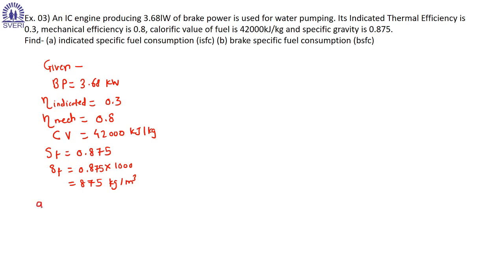So I'll start with part A, that is ISFC. So we know the formula for ISFC is equal to fuel consumed, in kilogram per hour, divided by indicated power.